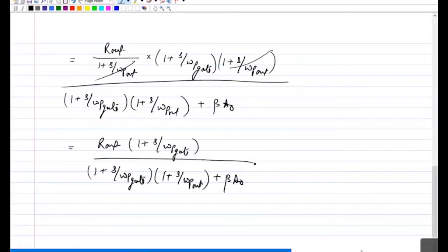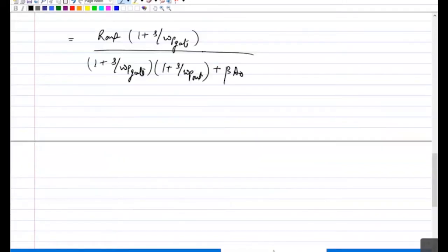Okay, so if I want to do the Bode plot for this, how many poles and zeros do you have here? Can anybody tell how many poles and zeros? 2 poles and 1 zero and 2 complex poles. How can you say it's a complex pole? Why do you say complex pole? I don't understand, where is the complex term here? I mean second order.